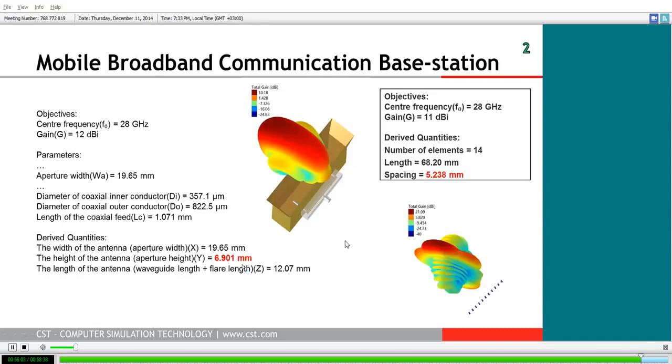And you can see here, if we arrange these in a hexagonal layout, we get a reasonable sectoral coverage with nice gain. If we compare this to what we obtain with our waveguide antenna-based array, we create at first our individual element, and in particular of note here we see that the waveguide height of our element is just shy of about 7 millimeters here.